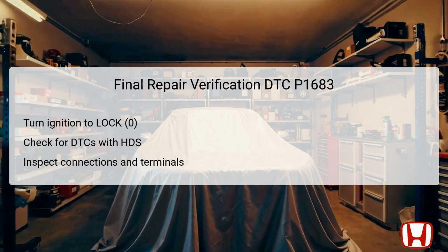Start by turning the ignition switch back to the lock 0 position for safety. After this, the technician should check for any pending or confirmed DTCs using the Honda Diagnostic System, HDS. This assessment is vital to ensure that no additional issues persist that could affect the vehicle's performance.